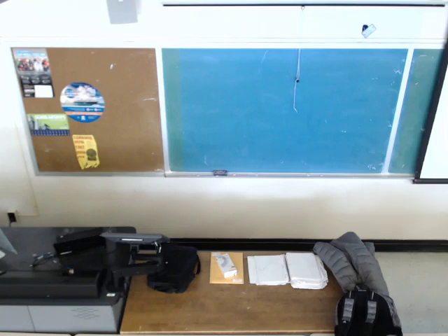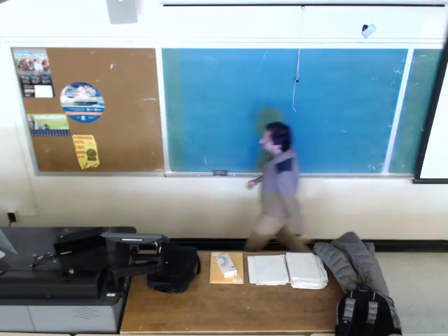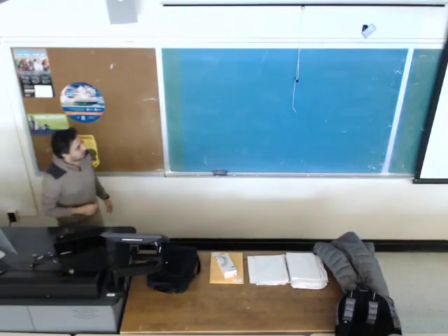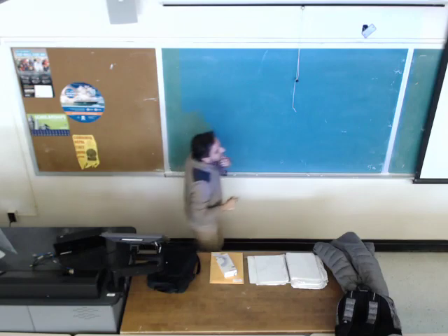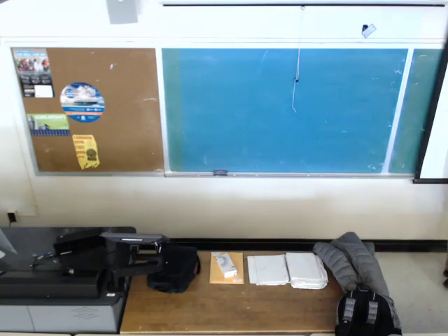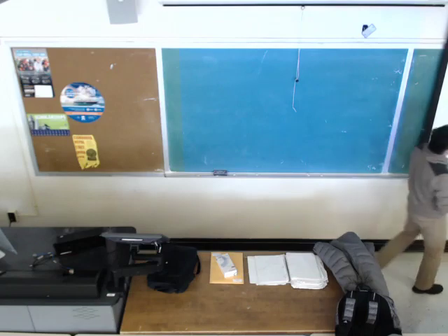So one of the joints is going to be at A1, the other one would be at B1. So 4 joints would be OA, A1, B1, and OB. Now, for this rigid body, you have the coordinates of these 2 joints. You are given them. So you would like to move this plane, these 2 joints, from this position to this position and this position. So how can we find the location of the ground joint?